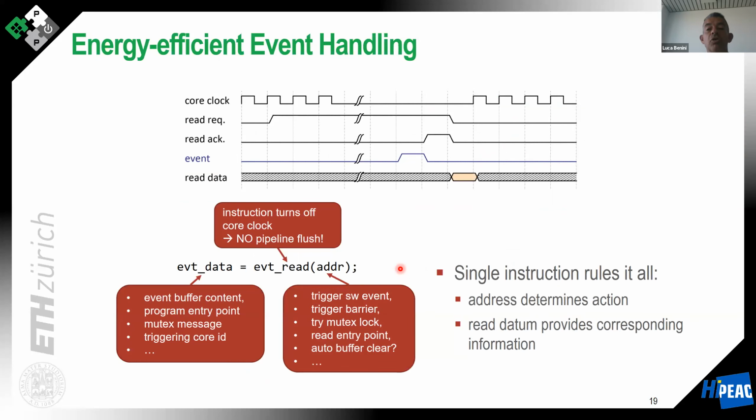So without going too much into details, the access to this synchronizer is implemented with a very small piece of software that essentially signals a memory mapped variable when the processor ends its parallel region, and this is done with a memory mapped access, so one load, and then the core goes into wait for event.